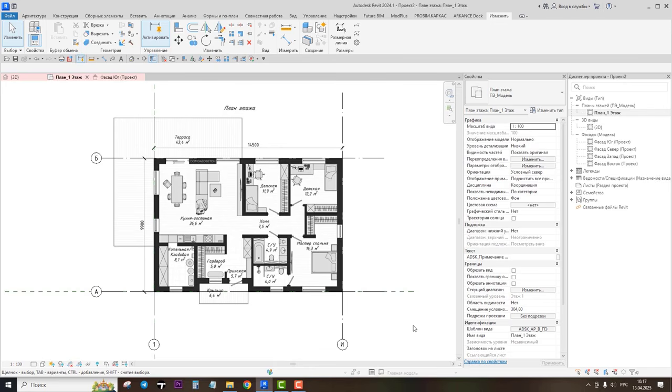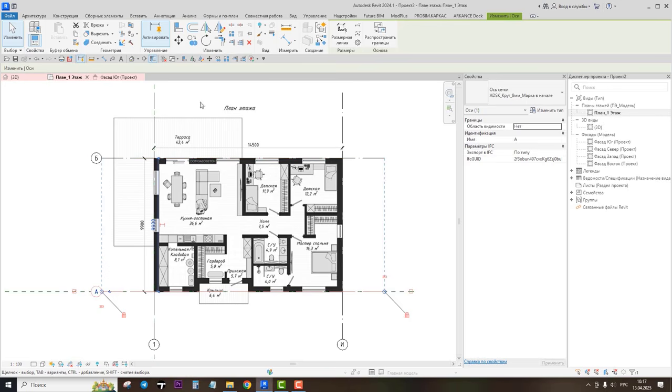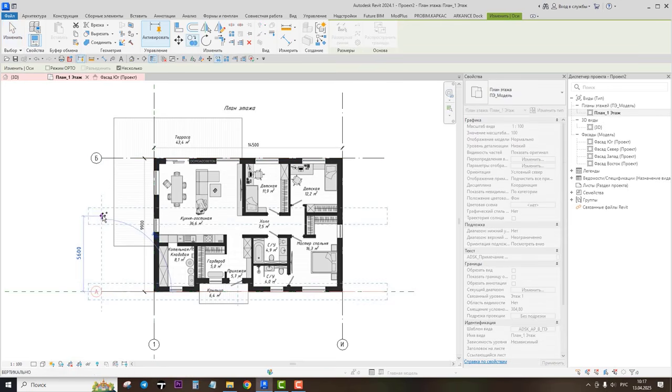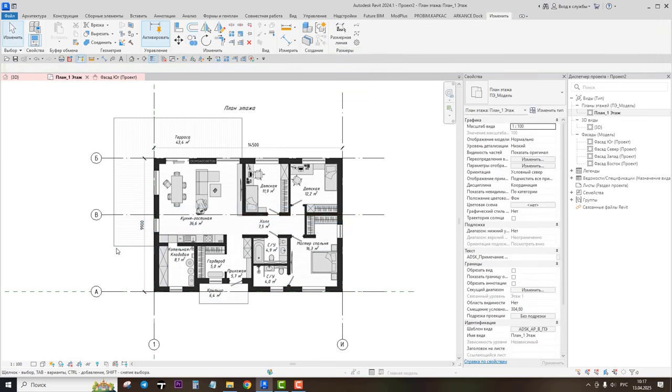Let's make one more horizontal grid line. You can select the line, copy, and in a free field, if you want to constrain move direction, you can use Shift on your keyboard. Or you can use this option here, this mark, constrain. If I mark it, this is a constant constraint. If I use Shift, this is a temporary one. Look, I press Shift and I make it active or inactive, okay? Okay, let's position the grid line.